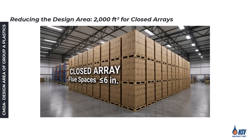If forklift operators set loads down even slightly more than 6 inches apart, the array is no longer considered closed, and our carefully calculated sprinkler discharge might suddenly become inadequate. Therefore, unless we can absolutely guarantee that the loads will always remain tightly packed, we should design our system safely assuming an open array.